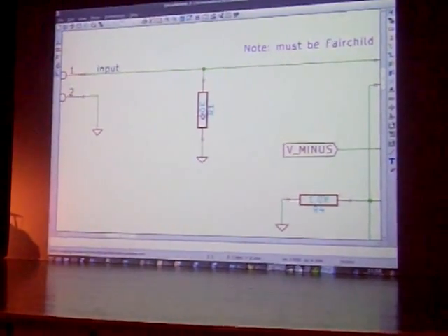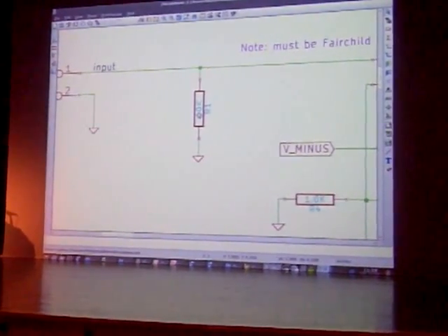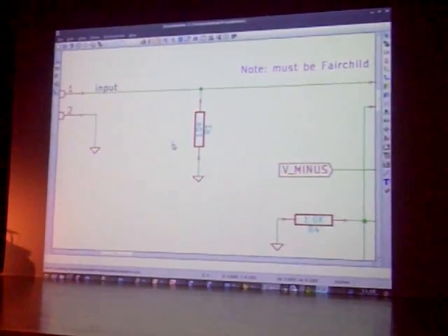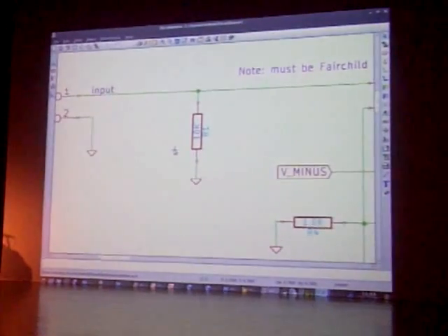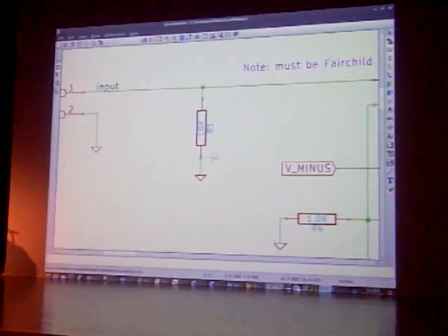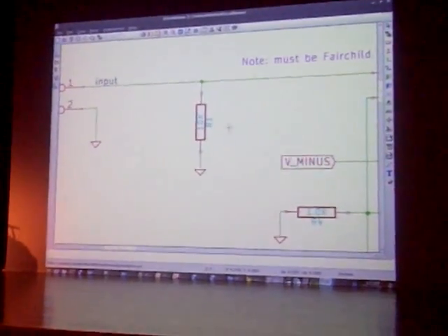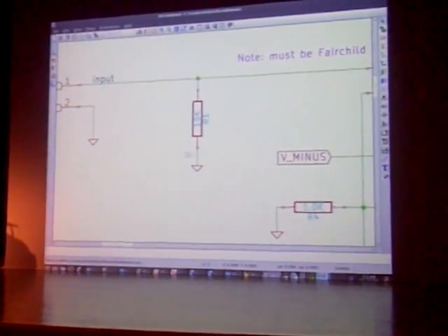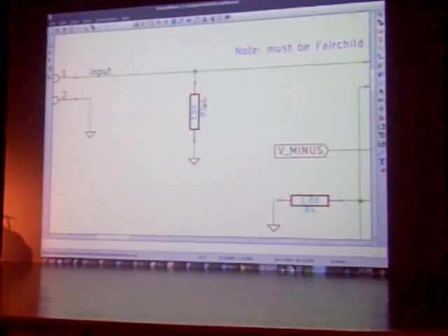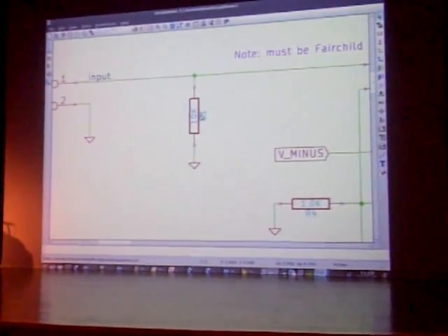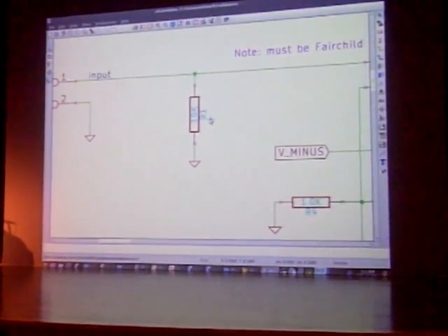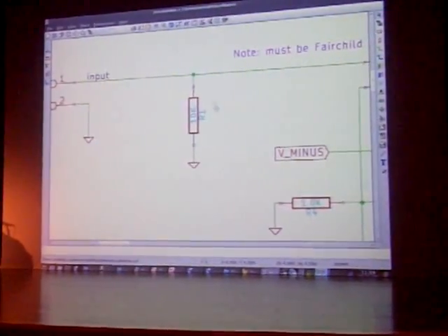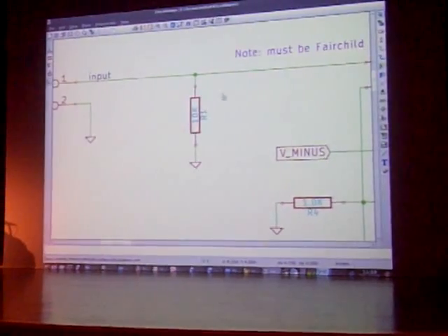It's not a quarter-watt resistor in a through-pin package. It's not a surface mount resistor in any one of a million different surface mount packages. I have not specified the package that this resistor is associated with. Because I haven't stated what package this is with, my PC board program doesn't know which footprint to use. Now this is done on purpose because this could change.